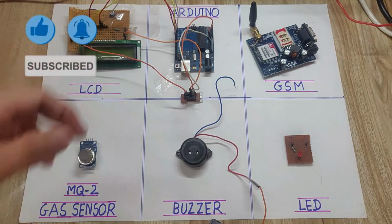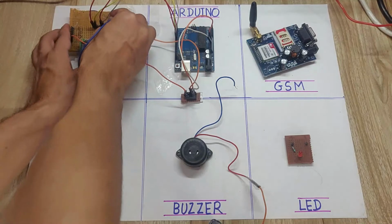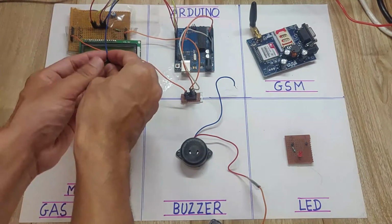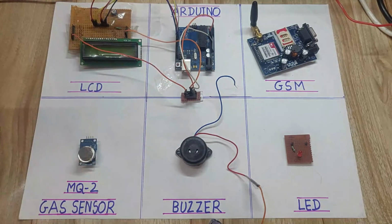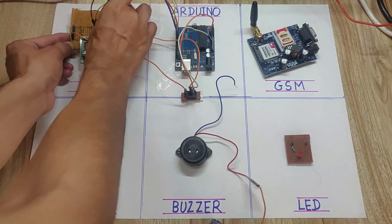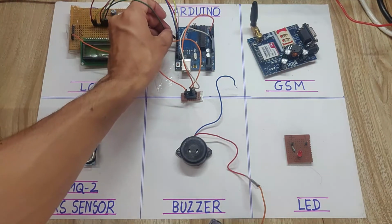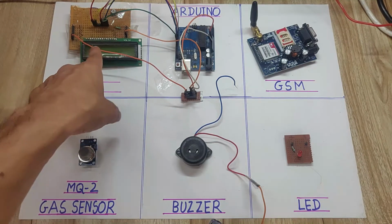Now the D6 pin of LCD should be connected to pin 8 of Arduino. So connect the D6 pin of LCD. So the D6 pin should be connected to pin 8 of Arduino. Then after that, the D7 pin of LCD should be connected to pin 9 of Arduino. So the D7 pin should be connected to pin 9 of Arduino. Okay, so in this way we completed the LCD connection with Arduino.